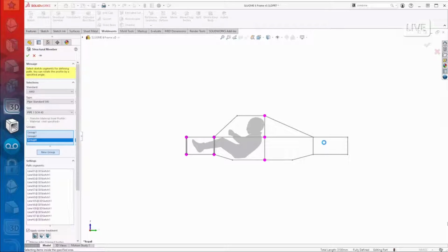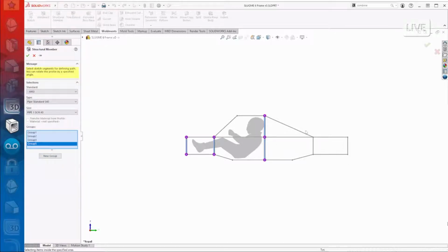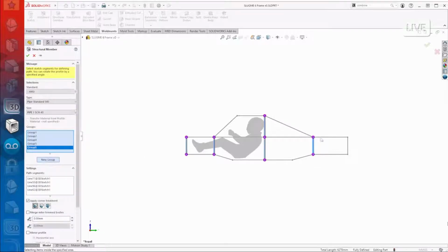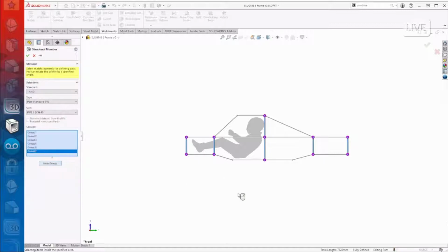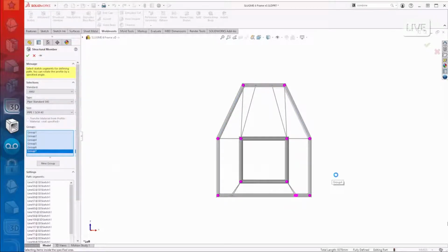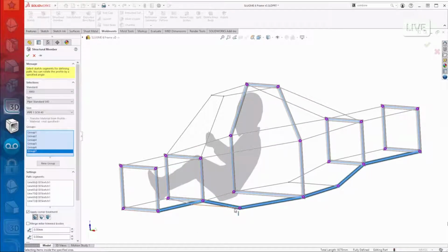About the connections to each other. But yes, you're absolutely right. Now that the audience understands what's going on, this is a much faster method. And one of the things that you want to pay attention to when you're doing weldments, and remember I said earlier, this enhancement, the groups, you're probably wondering why do you hype it up so much? It's not that big of a deal. The reason it's a big deal is because the order of trimming happens based on the order you select everything. So the most important members, the hoops, I created them first because they're all connected to each other. Right.